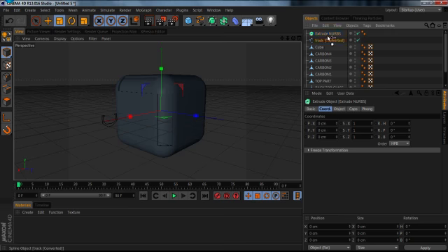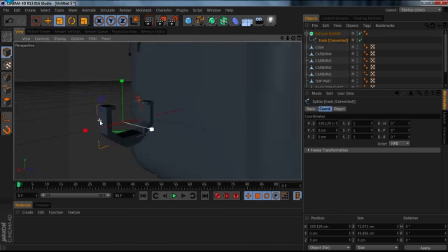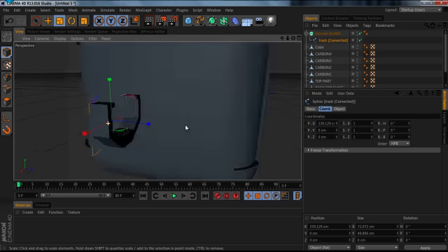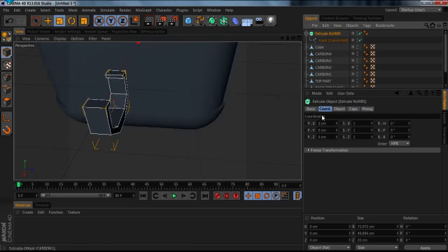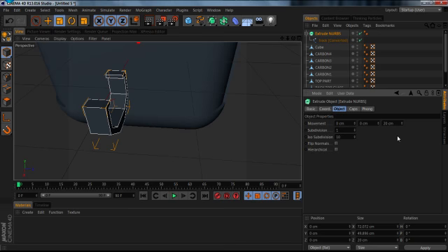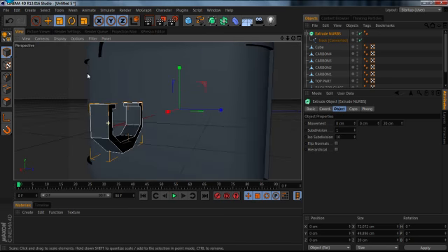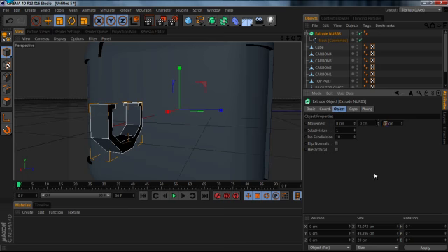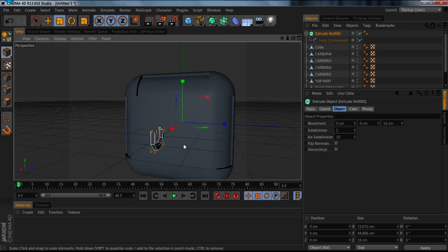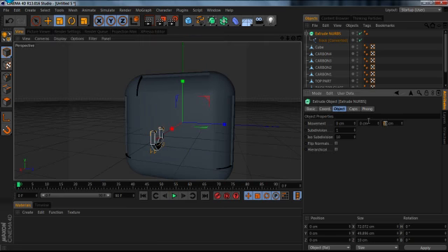And then I'm going to add that to an extrude node. So I'll drop it in an extrude node, zoom in, and then go in the extrude node properties, object, and as you can see, it's been extruded 20 centimeters in the z-axis. Whenever you see something like this, these digits, it stands for X, Y, and Z. So I don't need it to be that thick. Maybe let me try to make it half of that. Maybe even half is quite big. I'll make it 5 centimeters.